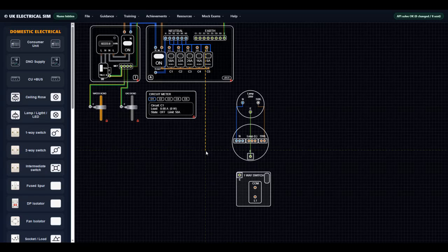When you reach the point where you want the wire to turn a corner, line up the guideline, left-click, and continue moving towards the destination terminal. Repeat that process until you reach the terminal you want to connect to. In this case, that will be terminal L1 on the ceiling rose loop. Once you click the terminal, the brown wire will be created.